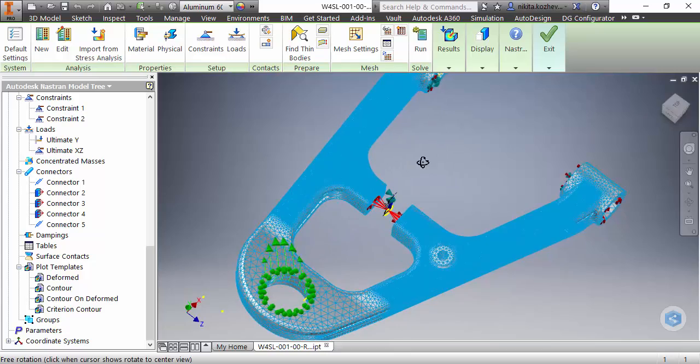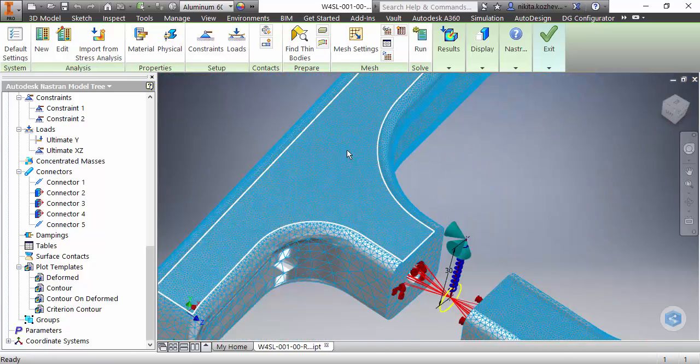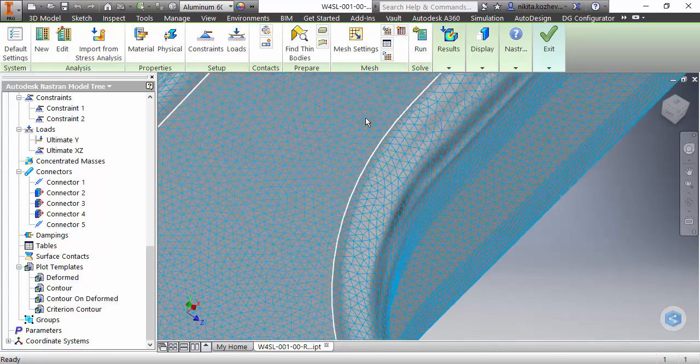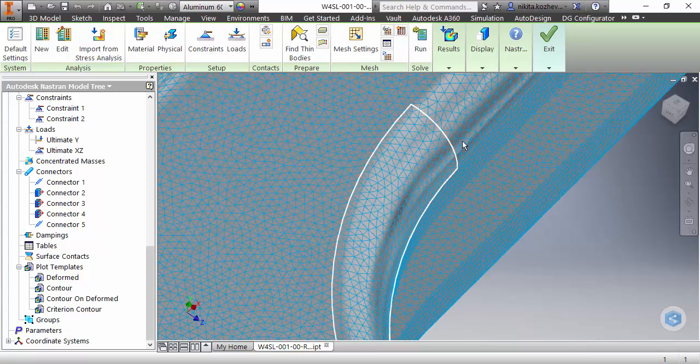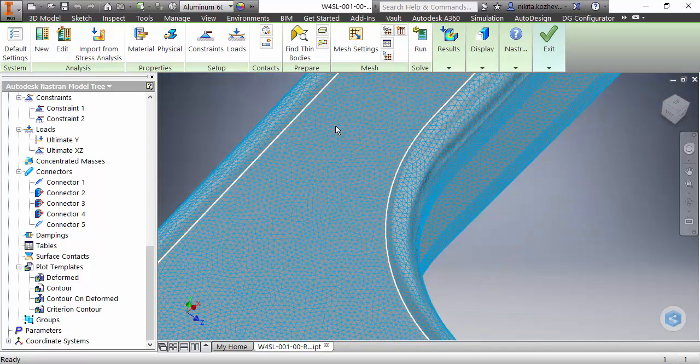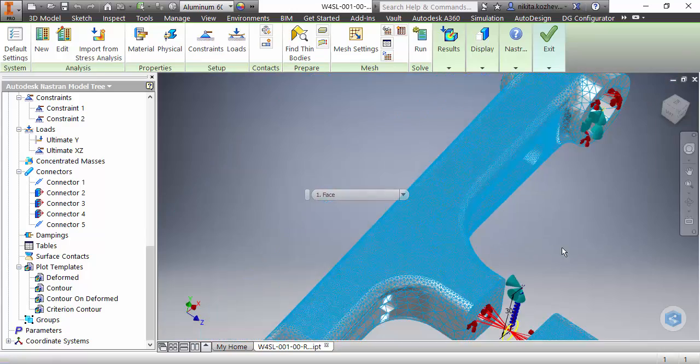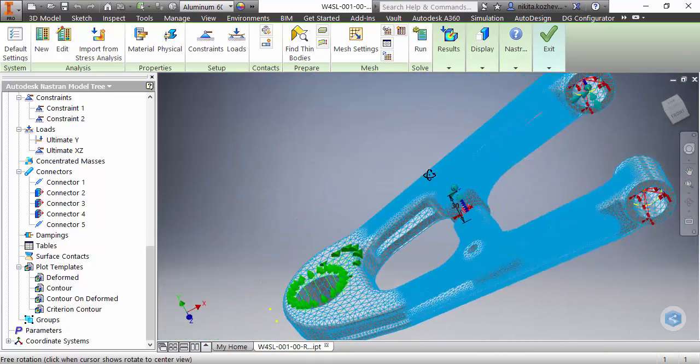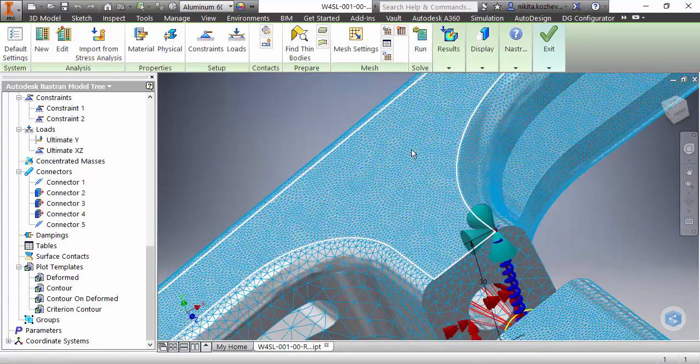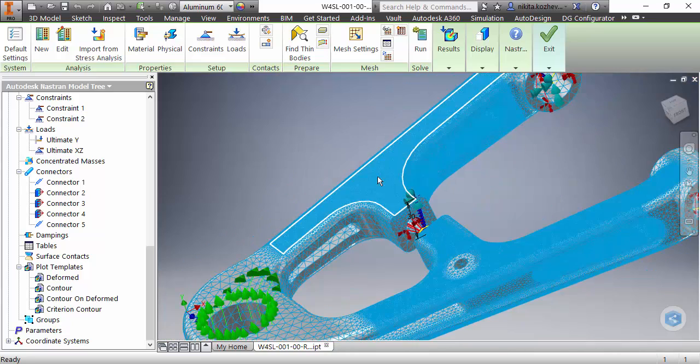The only difference is that the mesh resolution is even better here, because the nonlinear material models, and areas of plastic deformation in particular, require very high mesh accuracy, and that's why I reduced the mesh size to 1 millimeter here.